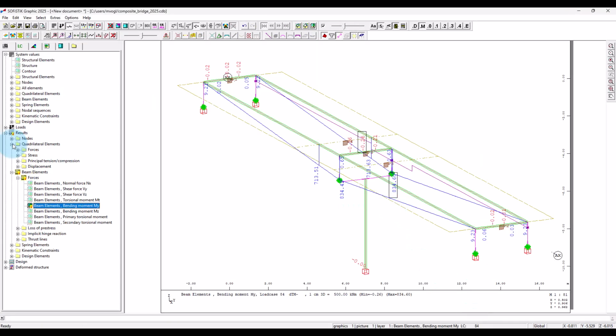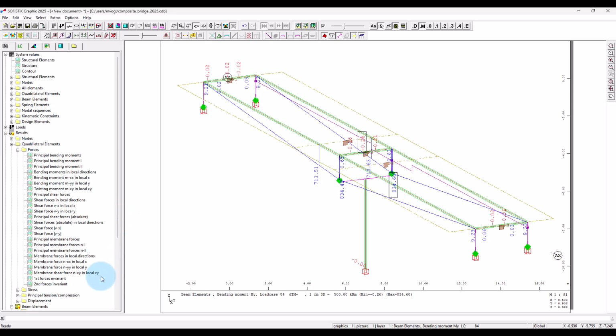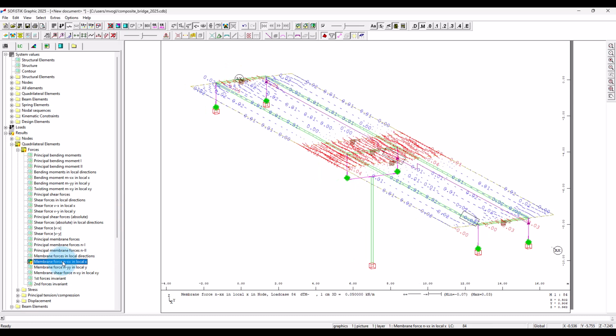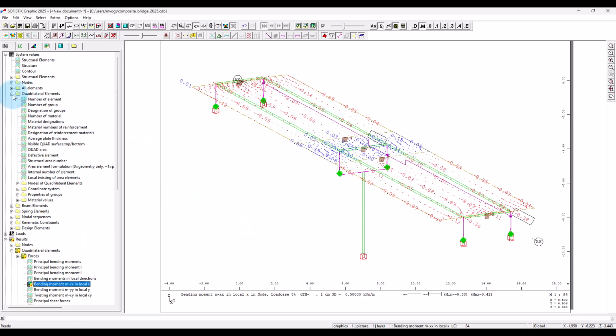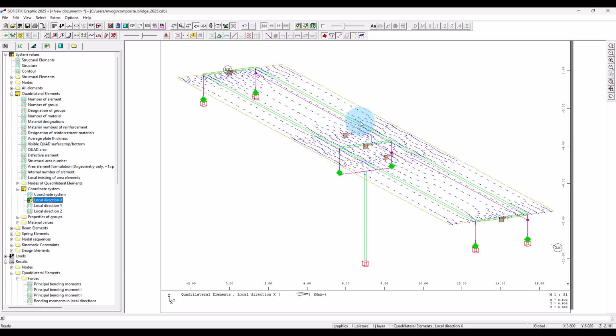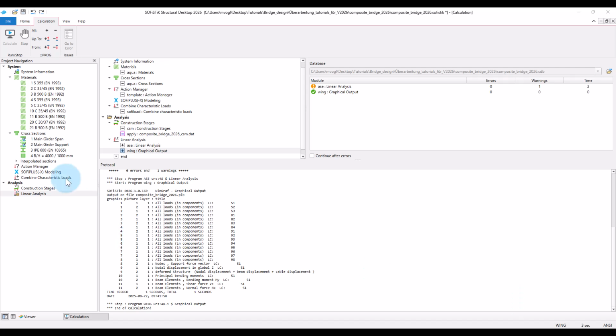You also can check it. So if we have longitudinal or axial stresses in the area elements, so axial direction of the bridge, therefore I go to forces, membrane forces, NXX. Okay, that's close to 0, that's fine. Same for the bending moment, MXX. Okay, I will also shortly check the X direction to be 100% sure. Yeah, okay, worked as it should. So temperature and settlement loads accomplished.